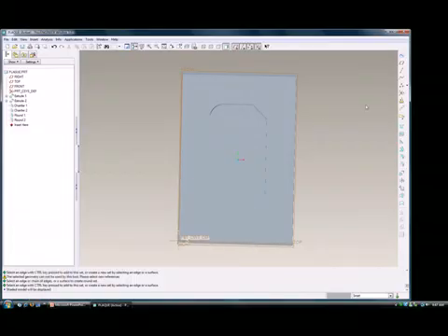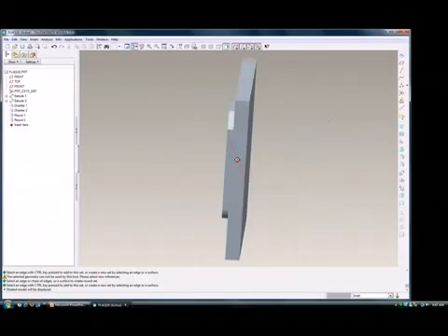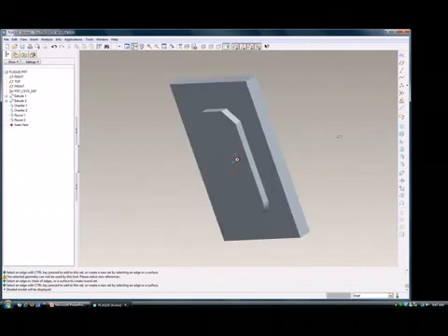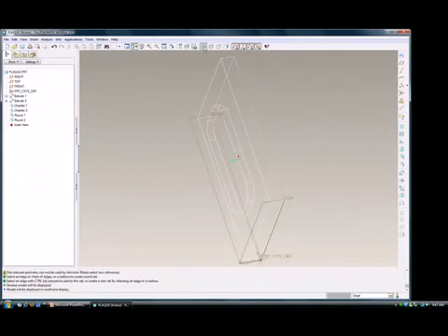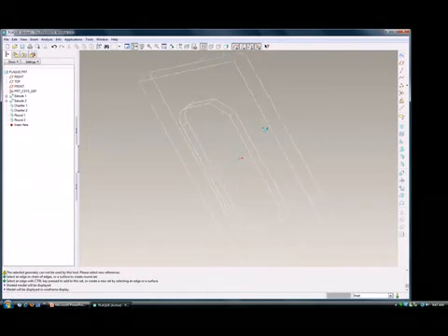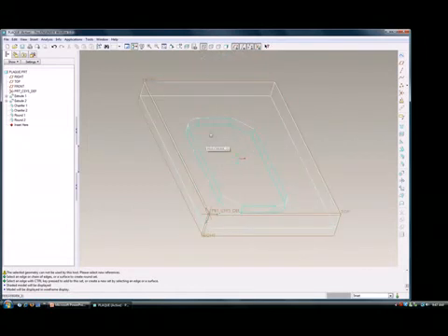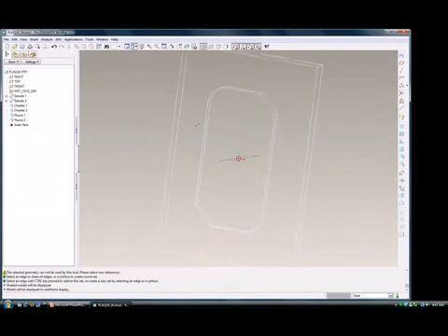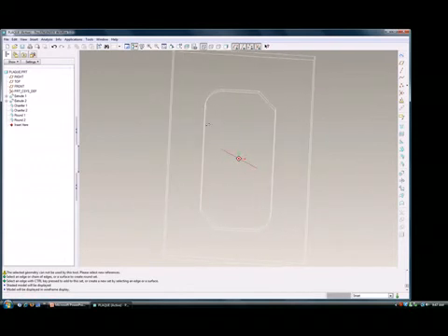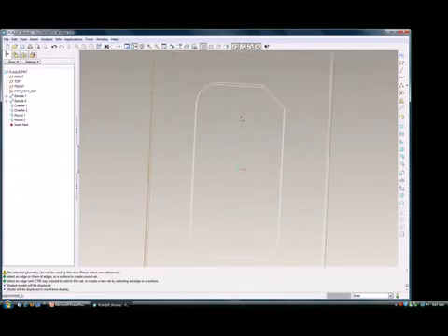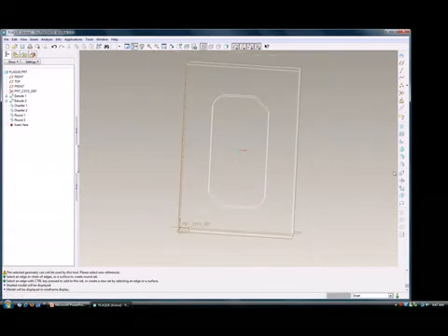To create a hole, we use the create hole button on Pro E. Let's go back to wireframe. I prefer wireframe. Sometimes when you move the block too much and it's hard to see and hard to move it back to the original place, you can always use Control D to make it the default view, and then rotate it again to get a better view. Or you can scroll the middle button to zoom in or zoom out. Okay, back to creating the hole on top.